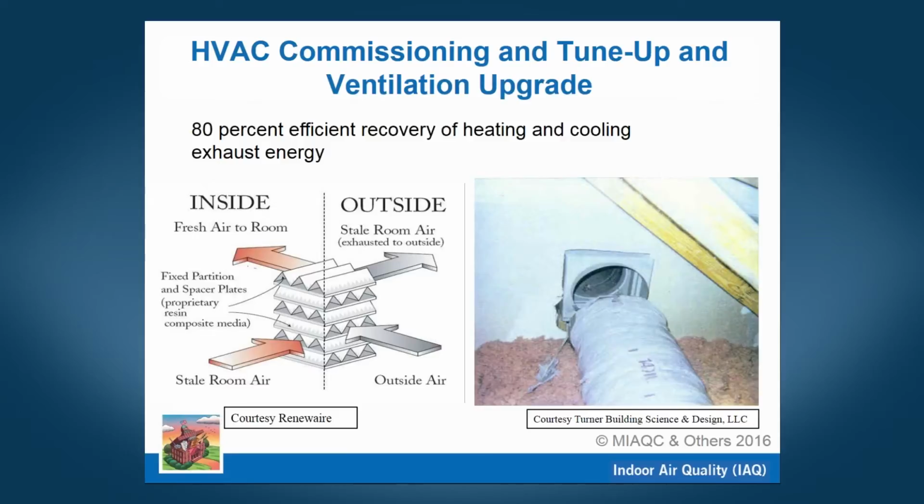That's the easy stuff. In many parts of the country today, as people look at upgrading ventilation, they'd look at energy recovery of some form for that ventilation. And there's readily available equipment today that would get you back about 80% of the energy you'd be throwing away, you can actually put back in the building again as part of that retrofit. So great advances in equipment out there and that typically becoming part of a renovation or upgrade.